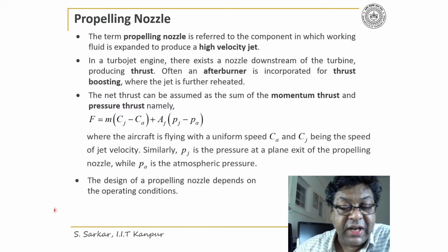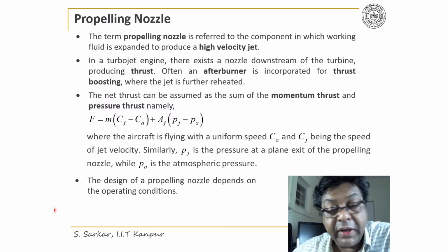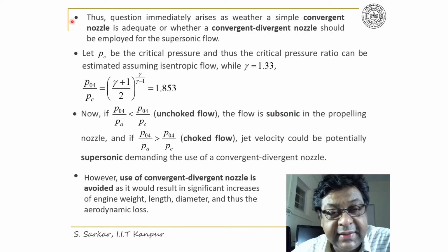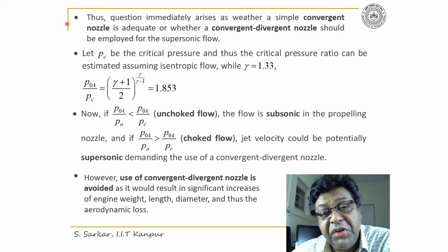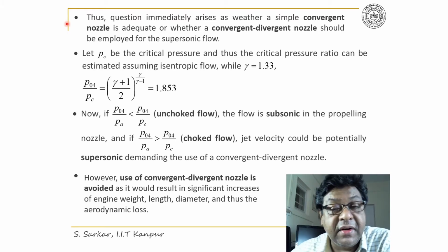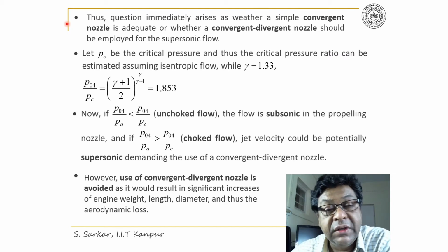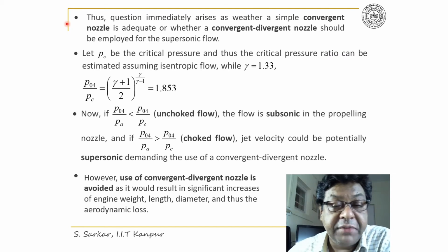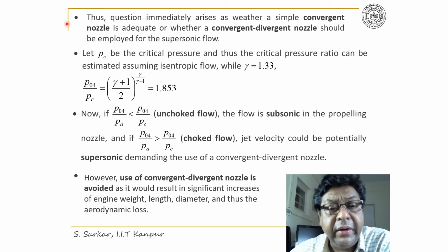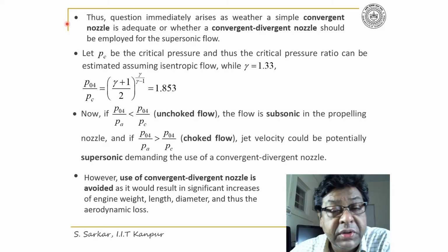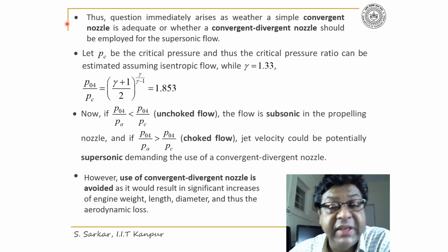Further, I'd like to tell you that the design of a propelling nozzle depends on the operating condition of the flight. Thus, the question immediately arises whether a simple convergent nozzle is adequate or whether a convergent divergent nozzle should be incorporated, particularly for supersonic flow. Here, let me assume the critical pressure Pc.